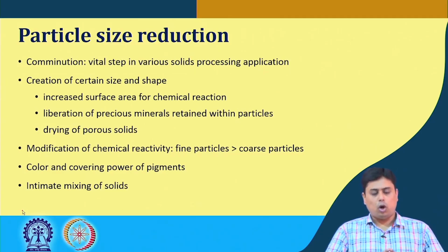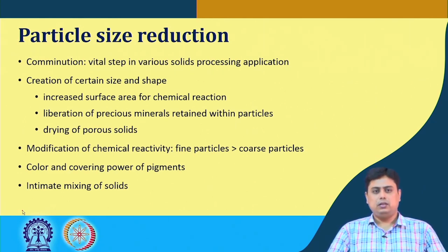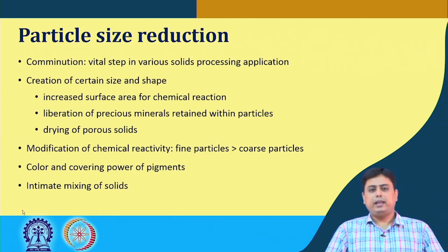On top of this, if we want different solids to be mixed, this intimate mixing of solids is enhanced when the particle sizes are reduced, and these are very extensively applied cases. When we have to mix two solid components to get something out of that, such mixing in a dry condition becomes easier when the size of the particles is reduced to a certain limit, keeping their identity the same. So, these are the various benefits of size reduction.